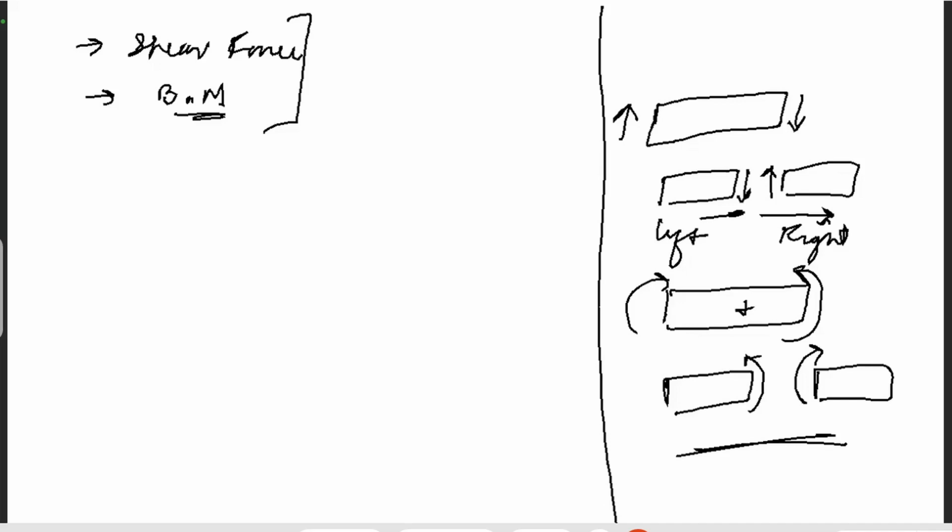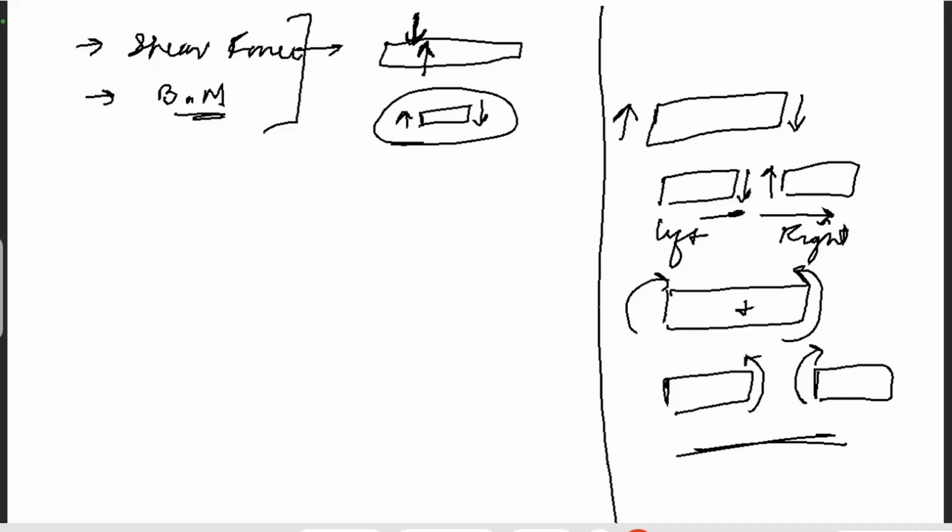And now, shearing means what? If you have this element, and there is some load at this point, there will be some force immediately after that point. This is shearing force. It is the force that goes in one direction on one side of the segment, and another comes on the other side of the segment. And bending moments, as you might already know, are actually couple moments. These forces tend to rotate the body, which is resisted by providing a resisting moment, and we need to calculate the resisting moment capacities of any segment. I think this is enough for today.